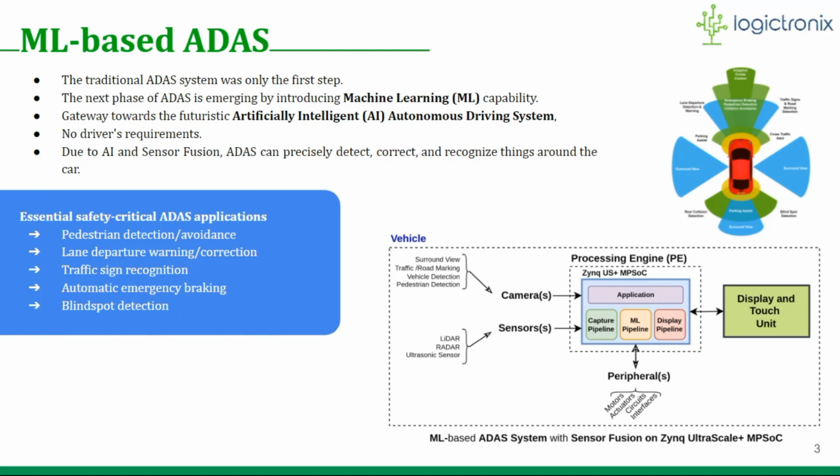The essential safety-critical ADAS applications include pedestrian detection, lane departure warning, traffic sign recognition, automatic emergency braking, blind spot detection. On the right hand side, you can see the block diagrammatic view of the ML-based ADAS system with sensor fusion on Zynq UltraScale+ MPSoC.